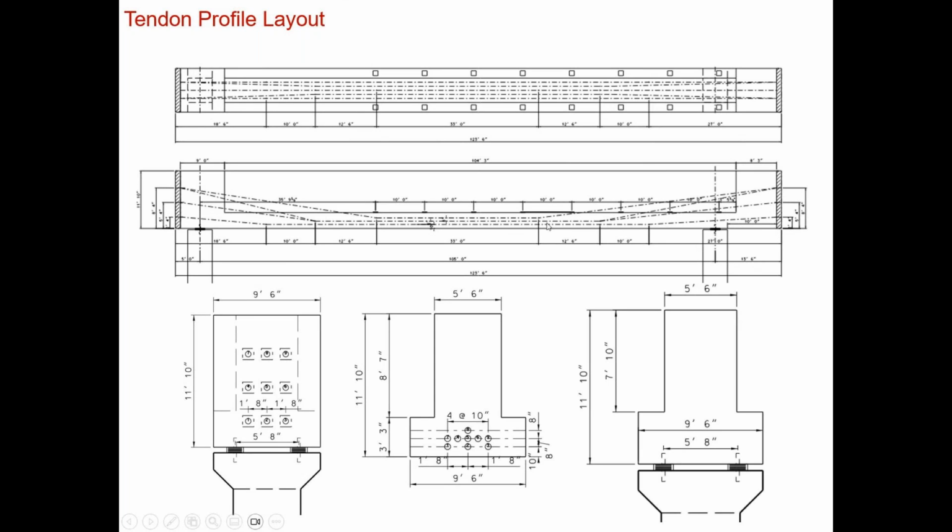Usually the post-tension members prefer using parabolic profiles or curved profiles. And there are some states that still like to use the draped profile, similar to what we do in pretension members. But at the end of the day, it's the same idea, the same effect, that you want to have the maximum utilization of the tendons right at mid-span, where you have the maximum moment. And this, of course, starts to drape upwards, where your moment fades away from the mid-span, going to the ends of the member.